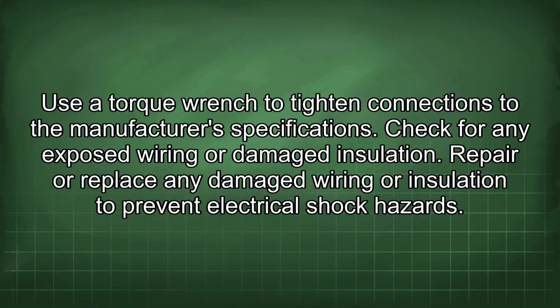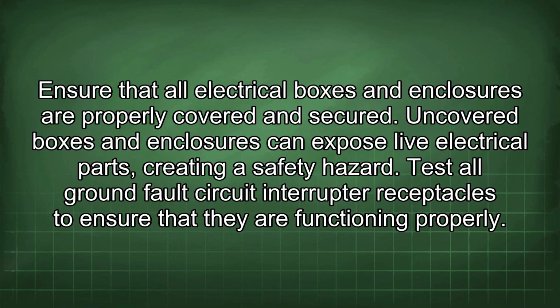Check for any exposed wiring or damaged insulation. Repair or replace any damaged wiring or insulation to prevent electrical shock hazards. Ensure that all electrical boxes and enclosures are properly covered and secured. Uncovered boxes and enclosures can expose live electrical parts, creating a safety hazard.